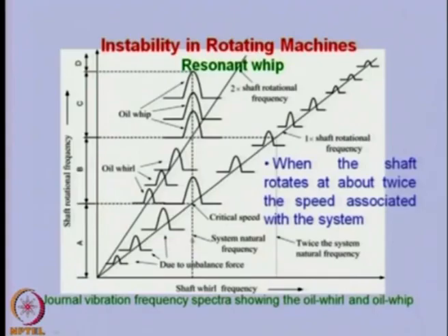Basically at this moment the rotor is actually rotating at twice the natural frequency, and the whirling is taking place at the natural frequency, and this particular phenomenon is nothing but the oil whip. This we will study in more detail as we go into the subject.